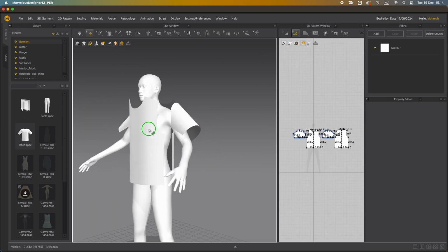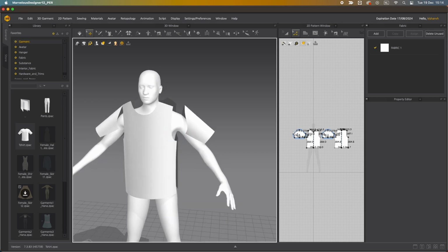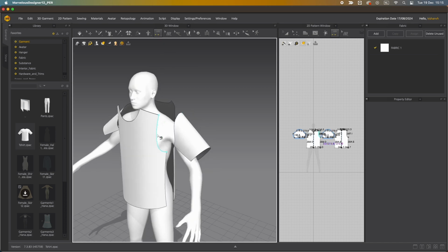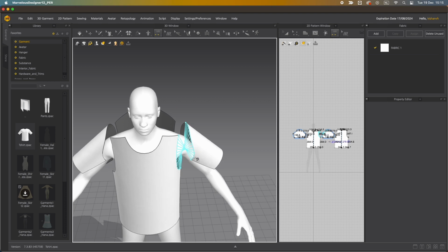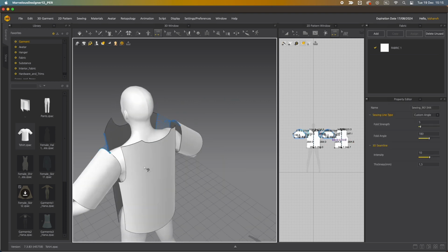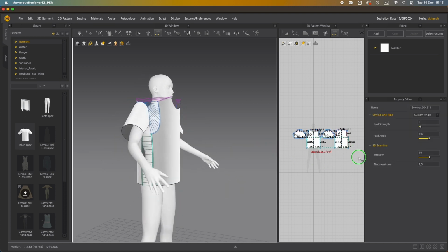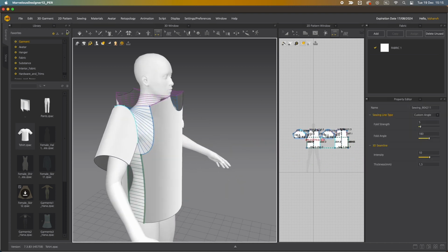When you are confident that your garment is complete, it's time for the seaming process. In the 3D window, navigate to the segment sewing. Begin by selecting one segment, then choose a second segment to get an overview of the sewing connections. Ensure that the seam lines are straight, but not in an X shape. Consider the logical connections between garment patterns, where the t-shirt would have seams, for example, shoulders, sides, sleeves with back and front garment. Continue until all sides are sewn.